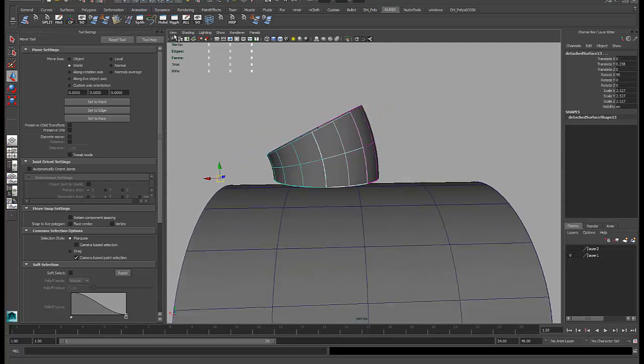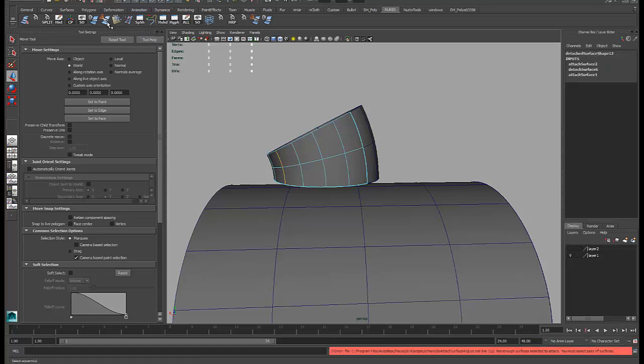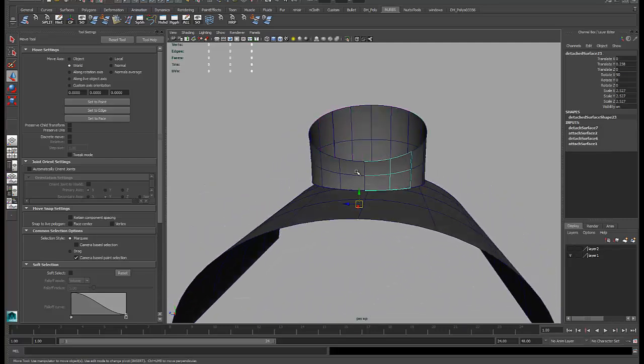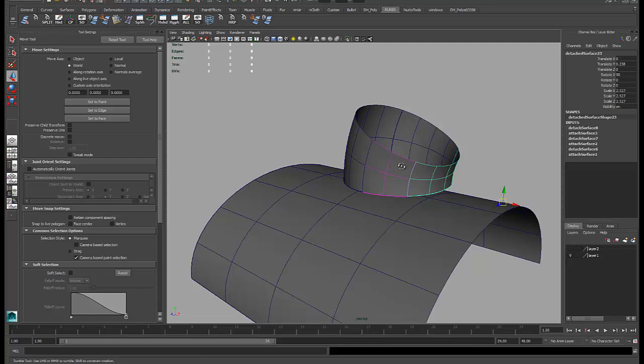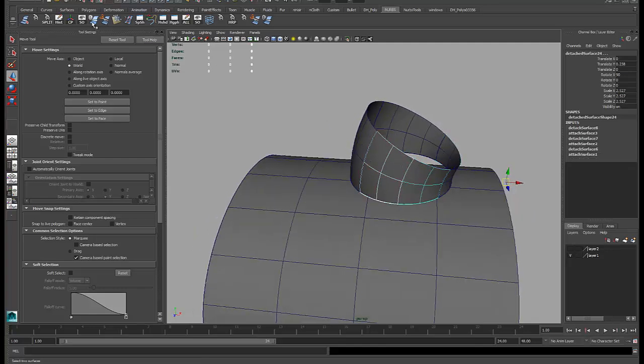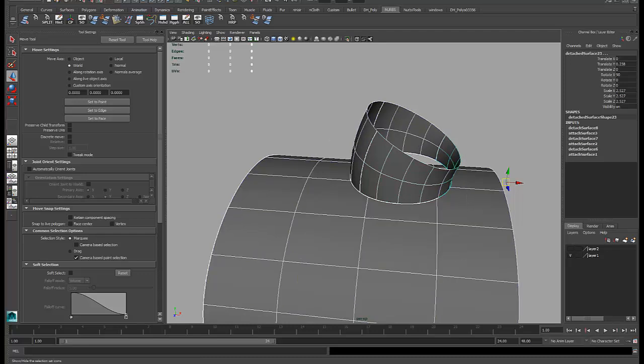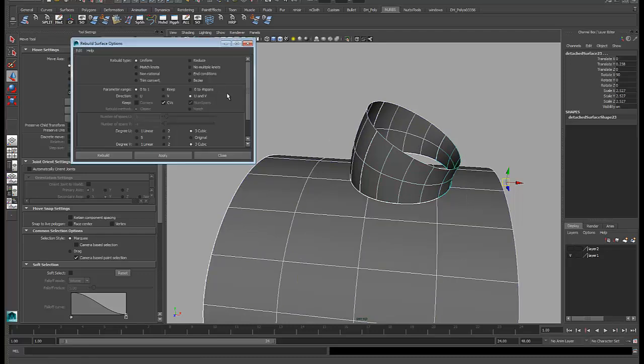I'll take these two pieces and attach them, and then take the 4-span surface, 1, 2, 3, 4, and I'll select this isoparm and detach it there. I'll take these two and attach them, and I'll take 1, 2, 3, 4 and detach them there. So now I still have 4. Oh, these two I need to attach then also. Okay, let's delete all the construction history, and I'll rebuild these, keeping the CVs.